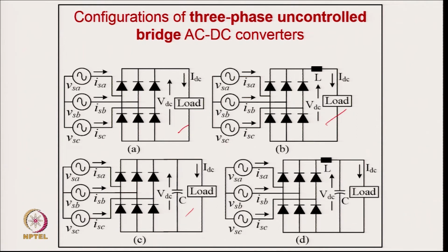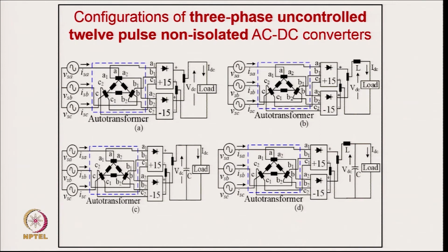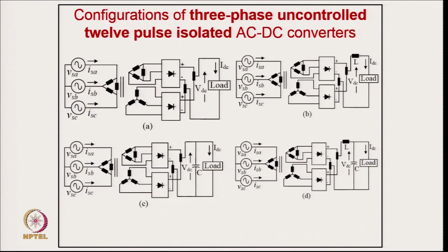So, all these conventional converters draw very high harmonic currents. And this is a 12 pulse with no filter, with inductive filter, capacitive filter. As you increase the number of pulses, if it is 12, the harmonics below the 11th are eliminated automatically because of the design and construction, but higher order harmonics will still be there substantially. So, you will still have around 15 to 20% THD in the supply current, which is not permitted; you allow only less than 5% or so.